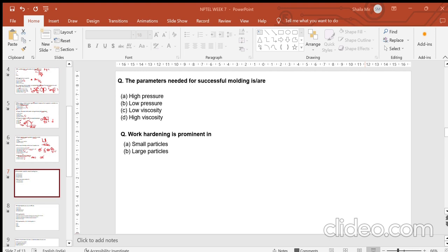First you are given the density of copper, and it is mixed with 2 weight percent cellulose, and the density of the cellulose is given. This is a hypothetical example. So how will we calculate the theoretical density based on the rule of mixtures? We will say weight fraction of A multiplied by the density of A, plus the weight fraction of B multiplied by the density of B. The weight fraction of A, copper here, because the 2% is cellulose and the rest is copper, would be 0.98.